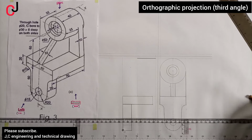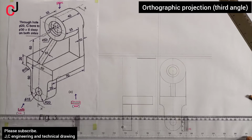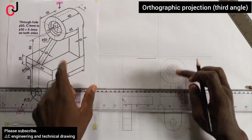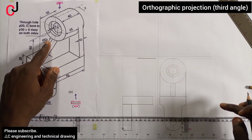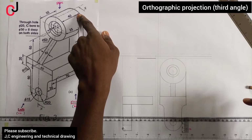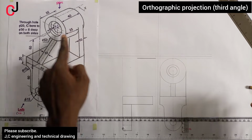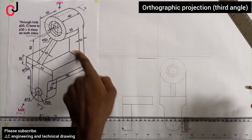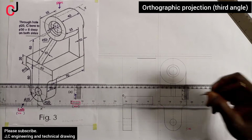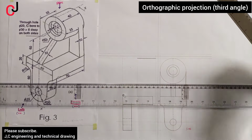Now you can see that we have a total diameter of 60 millimeters. So what you need to do, this is looking at from the side view. Now this is our side view, which is 60 millimeter. Now if you're looking at it from here, it becomes what? Here is 40 millimeter, but this still remains the same. The height of this shape still remains the same as 60 millimeter while looking at it from the front view. So from here to here is 60 millimeter. So you just project from your side view, and then you outline.